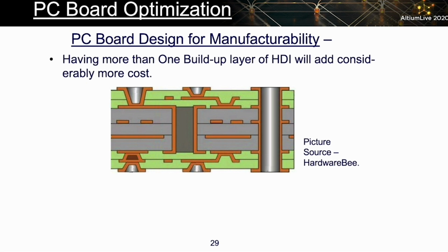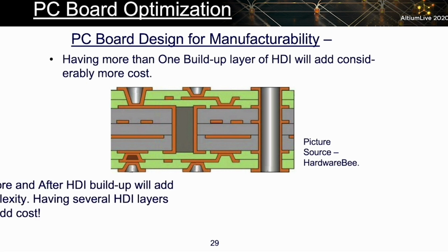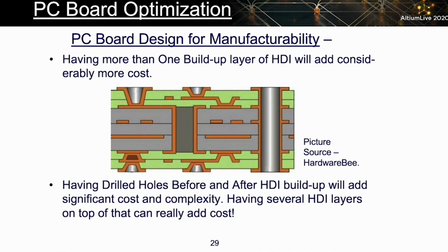The fact that you can connect any layer to any other layer doesn't mean you should. Having drilled holes after the HDI buildup layers really adds cost, as noted in the bottom bullet item on this slide. This is an expensive board. Don't go there unless you must.